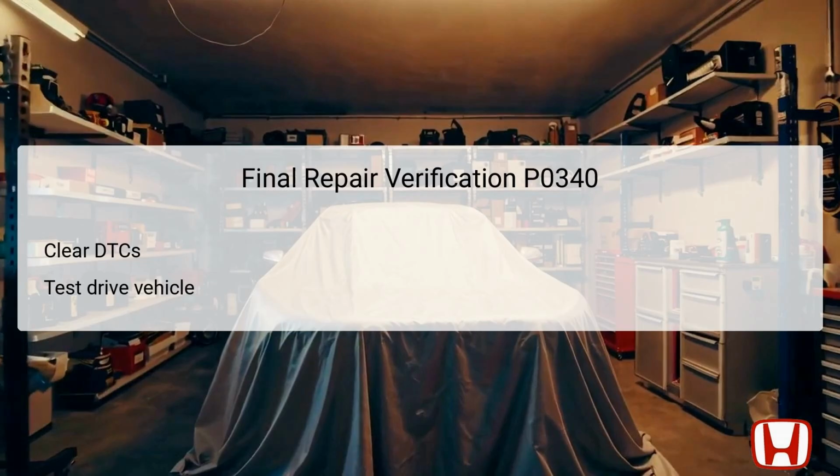Once repairs have been made and components replaced based on the previous diagnostic steps, the final verification is crucial to ensure that the P0340 code has been properly addressed. Begin this process by clearing the DTCs using the diagnostic scan tool. Clearing codes resets the PCM and allows you to monitor for any potential reoccurrences.